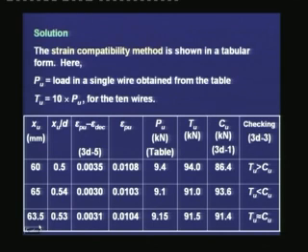After a few iterations, we have come to a value which is 63.5 millimeters, for which we find the tension to be 91.5 kilonewtons and the compression to be 91.4 kilonewtons, which are reasonably close, and we can say that the evaluation of the depth of the neutral axis and the forces have converged at the final values.